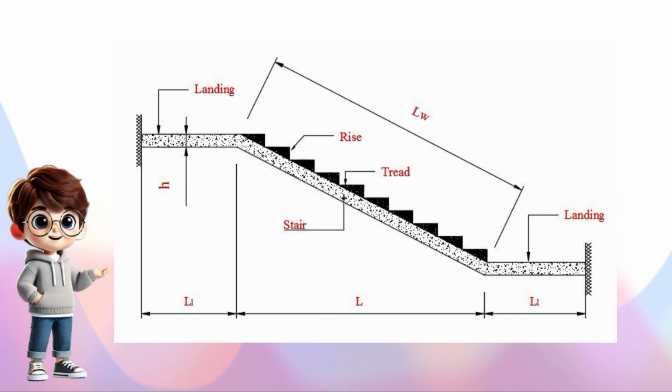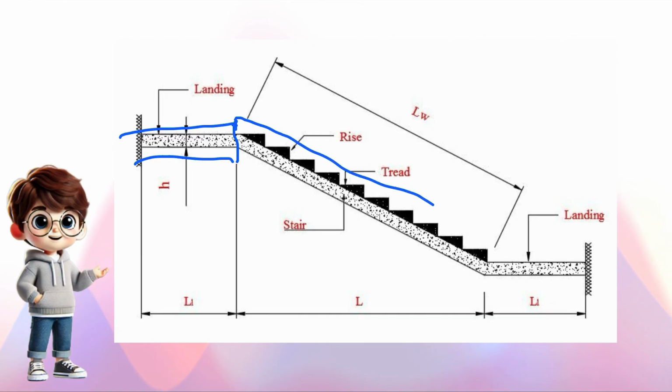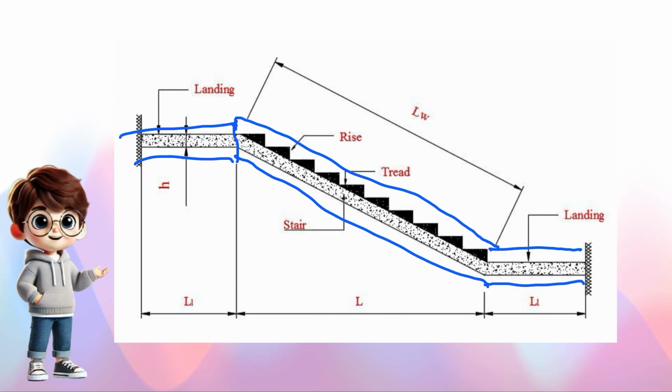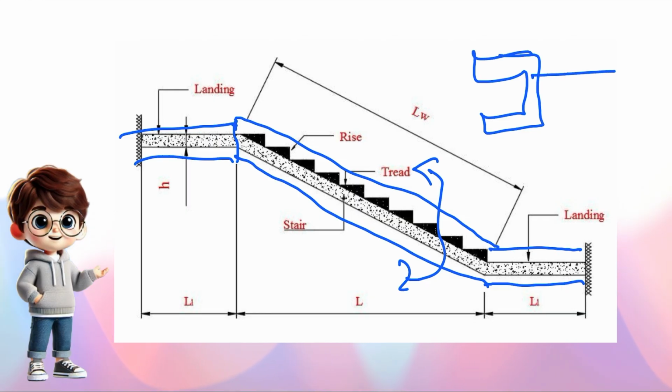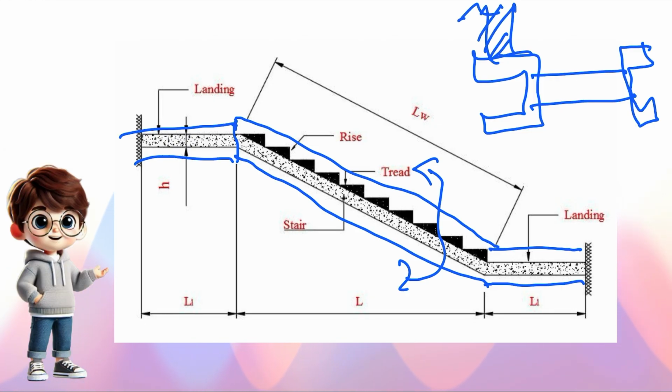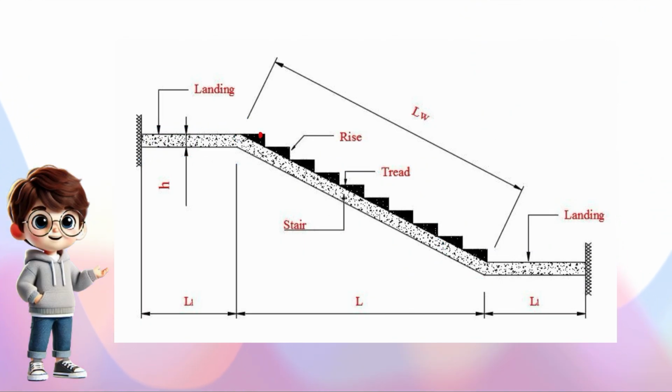And now usually how it will be is, this complete stair will be supported with stringers. Stringers are the channels which we will provide. If you just take this cross section, there will be one channel like this, and this will be the tread, and there will be another channel like this, and here we will get handrails on the channels. So the line which is connecting all these tips, we call this the nosing line.